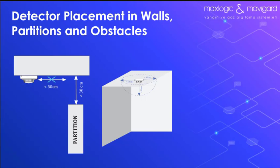Detectors, except optical beam smoke detectors, should not be mounted within 50 cm of any wall or partition. If the room is narrower than 1 meter, the detector can be applied to the center of the room or should be installed close to its center.